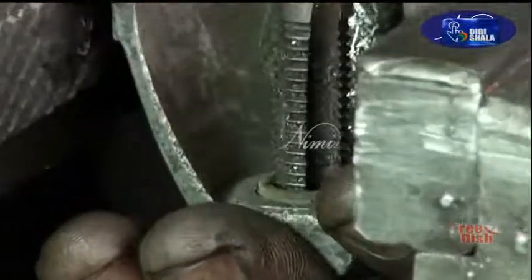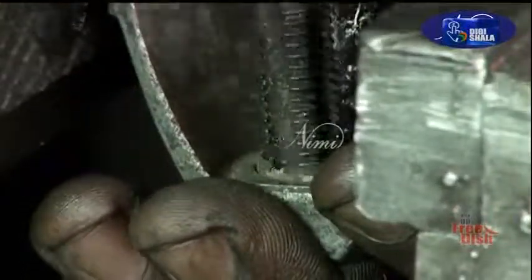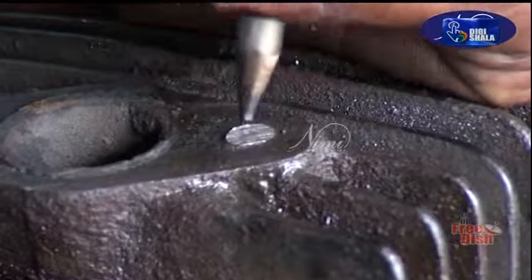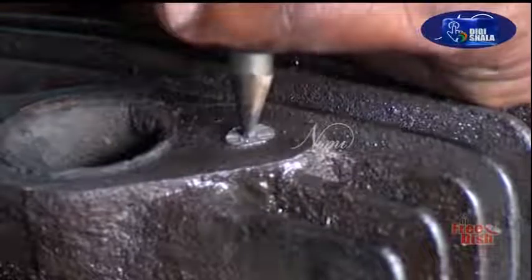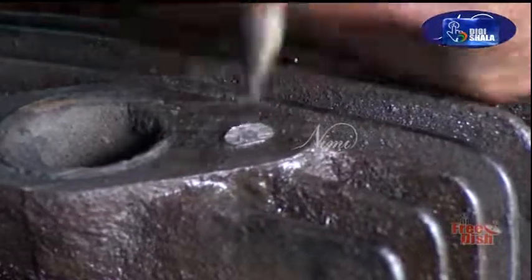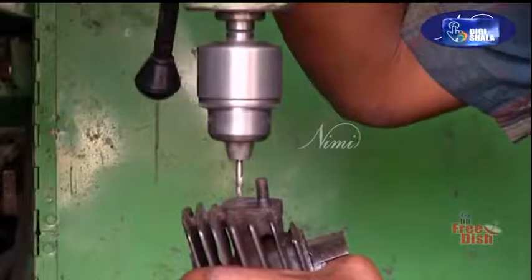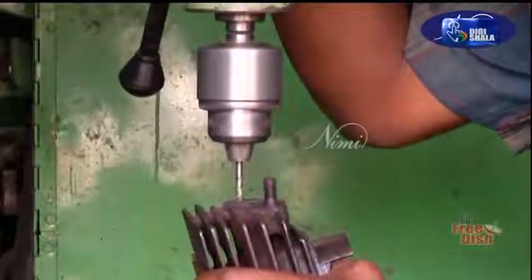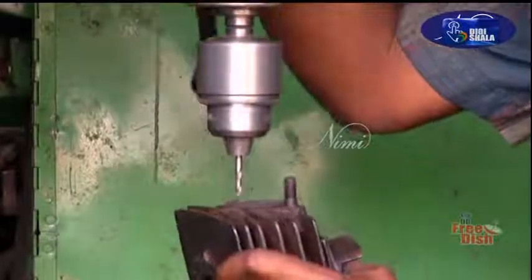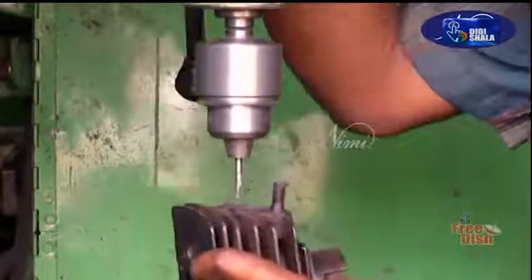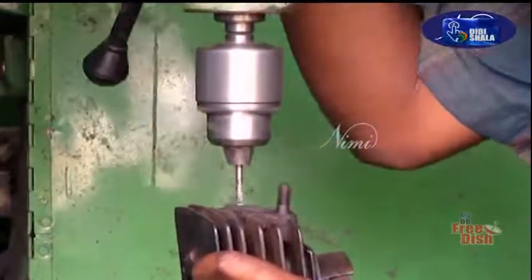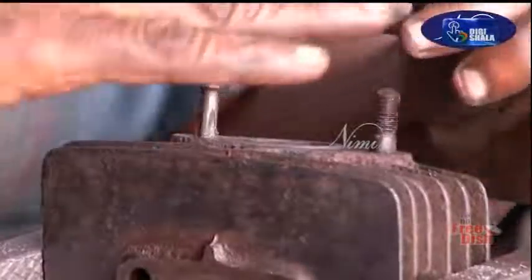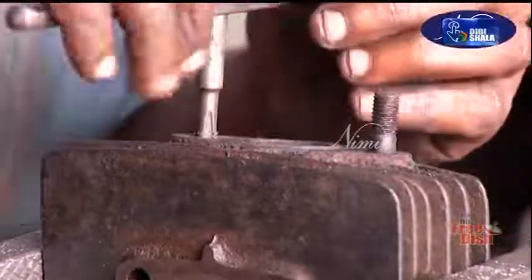To remove the broken stud or bolt below the surface, a stud extractor is to be used. Locate the center of the broken stud. Center punch it. Drill in the center of the broken stud by using a drill of diameter little less than the root diameter of the thread on stud. Use the right easy out number of the extractor. Turn the extractor to force out the broken part of the stud.